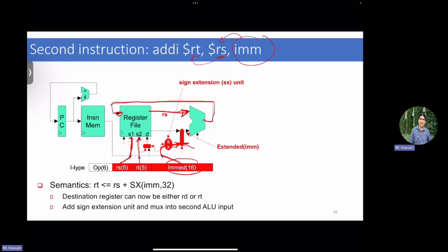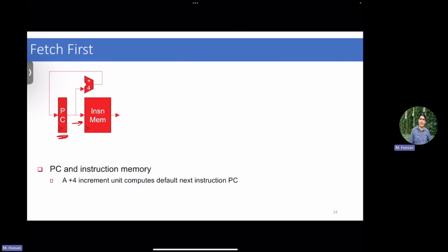Why do I have it? Because if you go one step back, if it was only an add instruction, it's just very simple. If you are building a processor to only do this instruction, what I'm going to do is send your two source operands to your register file, read their data, do the addition, obtain the result, and write it back. I'm done. But if I want to support a processor that has the two types of operations, add and addi, right now the ALU will still, in both cases, need to read one source from the register file.